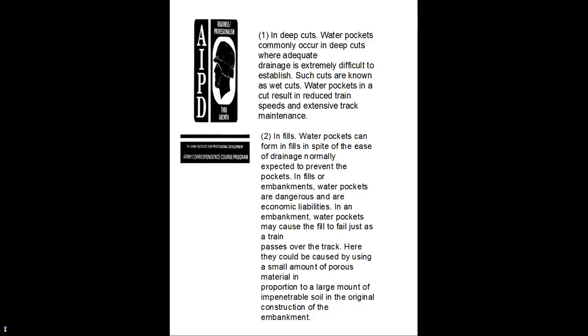Water pockets can present problems in deep cuts and fills, under heavy traffic, and in freezing weather. 1. Deep cuts. Water pockets commonly occur in deep cuts where adequate drainage is extremely difficult to establish. Such cuts are known as wet cuts. Water pockets can result in reduced train speeds and excessive track maintenance. 2. Fills. Water pockets occur in fills in spite of the drainage normally expected to prevent them.